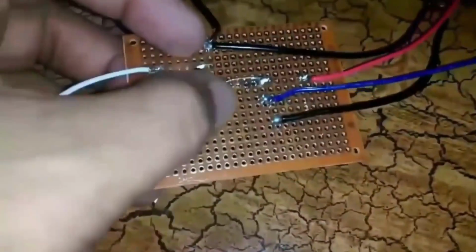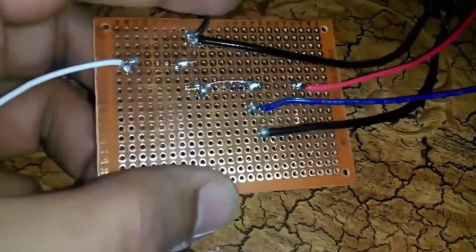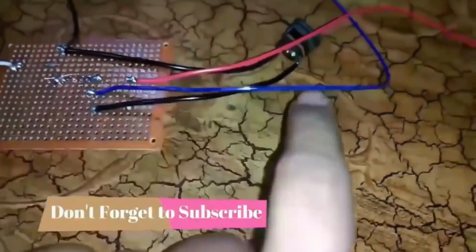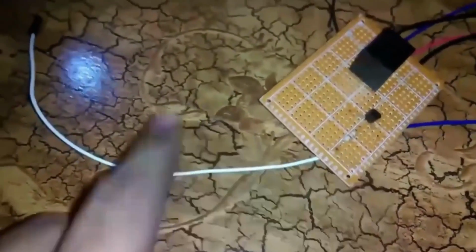So as you can see, the collector is connected with one side of the relay coil, and the other side is connected with the positive, and the ground wire is connected with the emitter, and there is another wire which will be connected with the Arduino ground, and this wire is coming from here and will be connected to pin 13 of the Arduino. Through this wire we will turn this relay on and off.